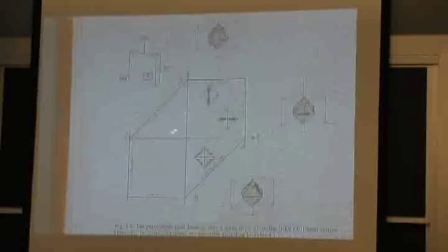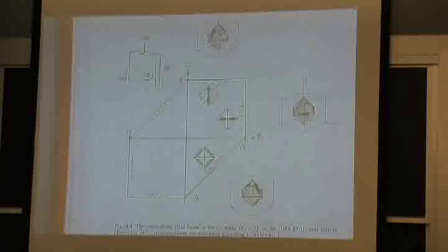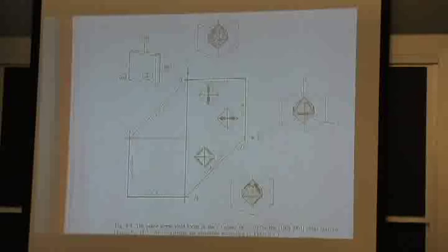And if you want to look at the slip planes, he's actually doing this for 111 slip planes in this particular case, which would be face-centered cubic, but it turns out because of the symmetry between directions and planes, between FCC and BCC, it works the same way if you do the math.